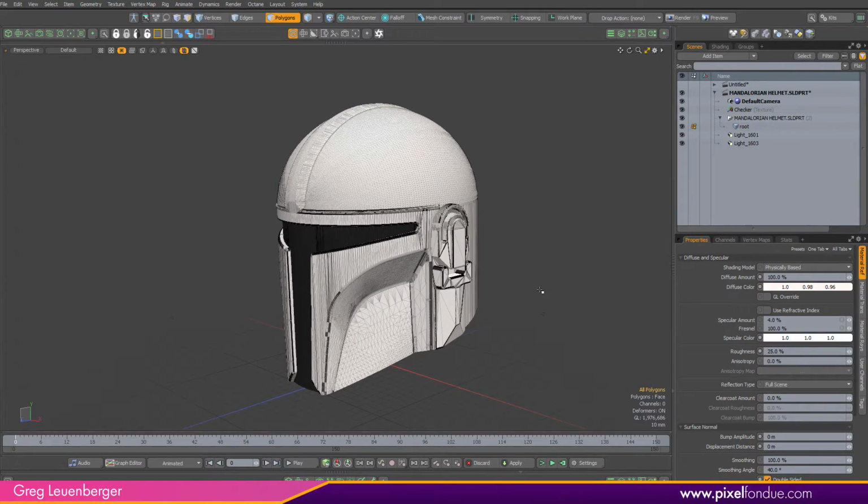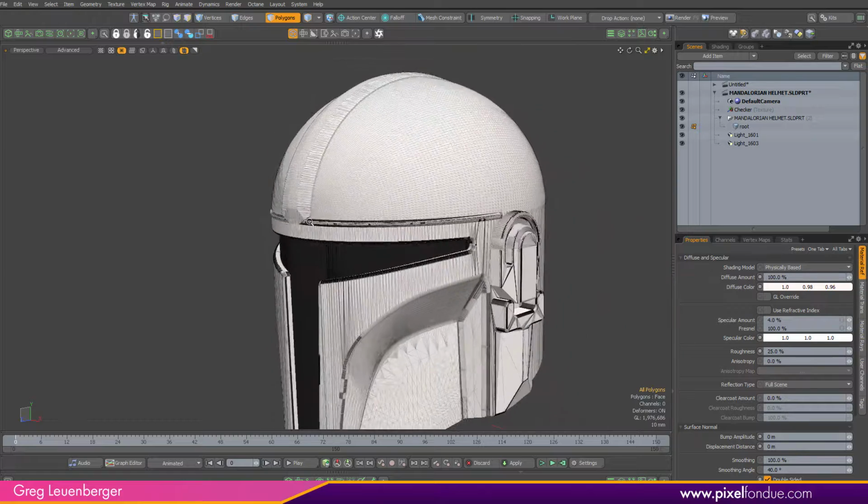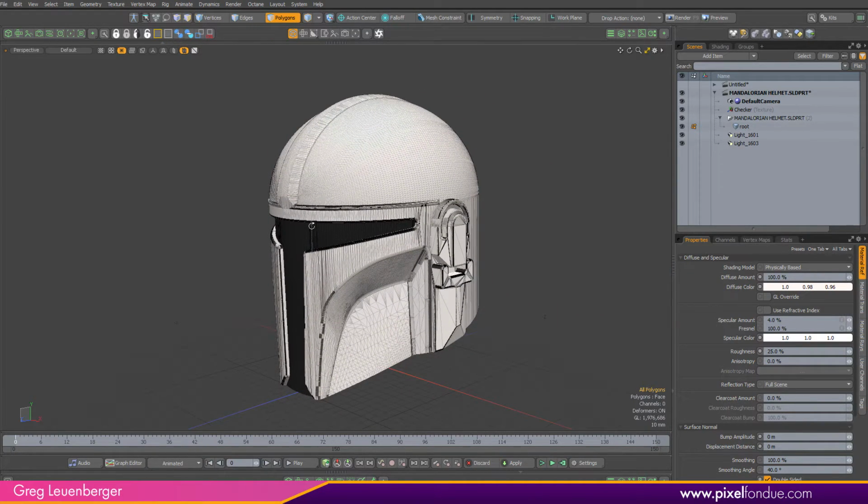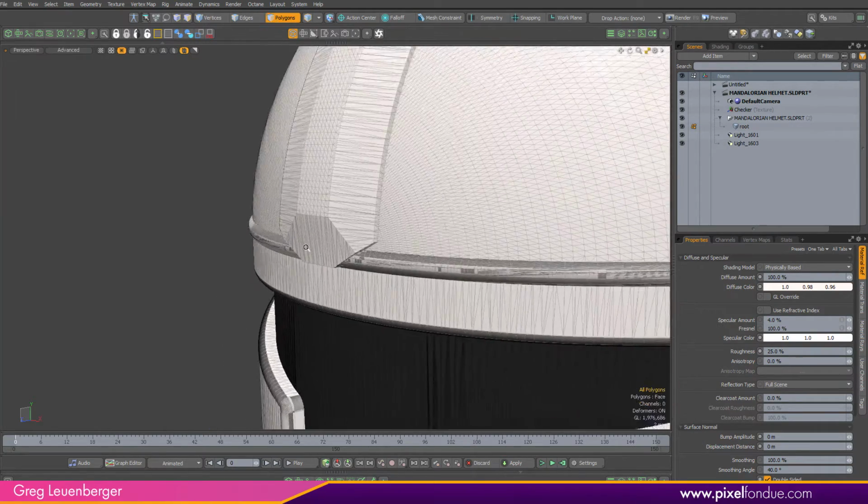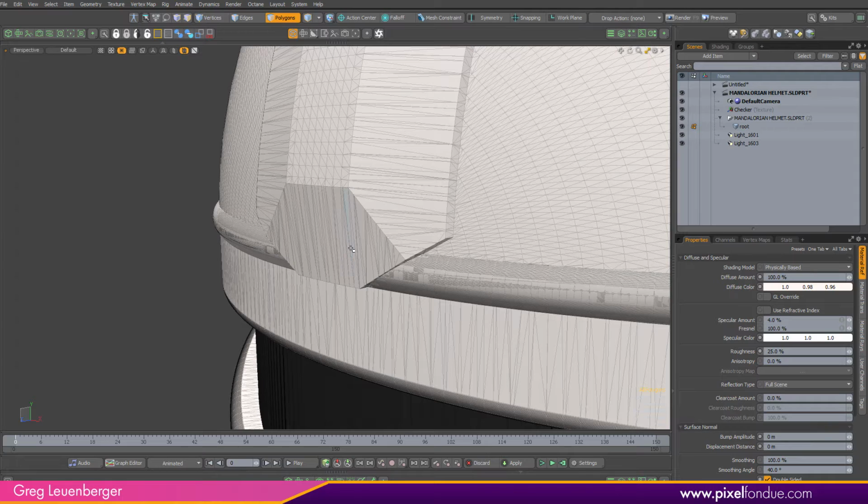And that's kind of it. The tessellation on these again is a bit of a crapshoot. There's no file requester for deciding if you want to adjust your tessellation on the import, right? So it doesn't bring in the file and ask if you want very fine detail with a ton of polygons or very rough with just a few. You just get what you get, and what you get is, I believe, based on the SolidWorks display properties.